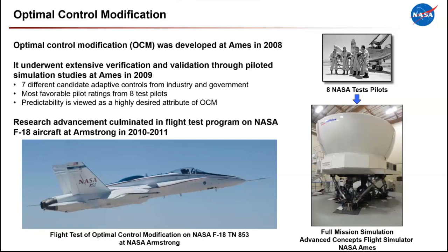We had 8 test pilots from NASA Armstrong and Ames participate in the study. We had 7 different controllers, and the pilots flew these controllers inside the ACFS, and then they provided Cooper-Harper ratings, which is a handling quality rating, and the optimal control modification received the most favorable rating from these pilots.